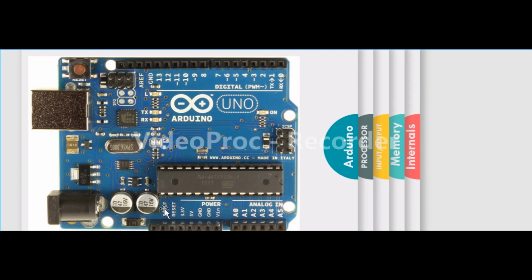There are three main ways you can actually power an Arduino board. One is the USB cable, another is the barrel jack, and you can also connect it using jumper wires to a source using the VIN pin right here. Now, these are going to be for output. The 3.3 volt and the 5 volt are output voltages that can be provided by the Arduino, and these are ground.